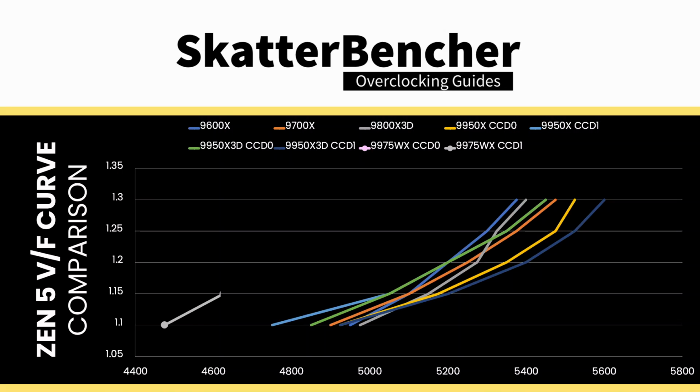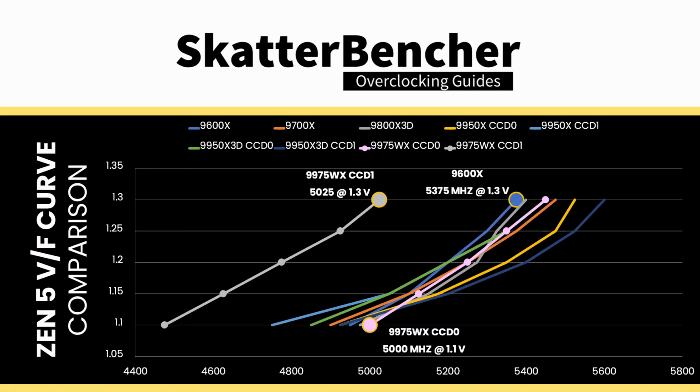Compared to the other Zen 5 VF curves I've been tracking over the course of the various SkatterBencher guides, we find that CCD 0 is an exceptional CCD. We can do 5 GHz at 1.1 volt. However, CCDs 1 to 3 are pretty bad. At 1.3 volt, they trail about 350 MHz behind the worst Zen 5 curve we tracked to date, and that's the one of the Ryzen 5 9600X.